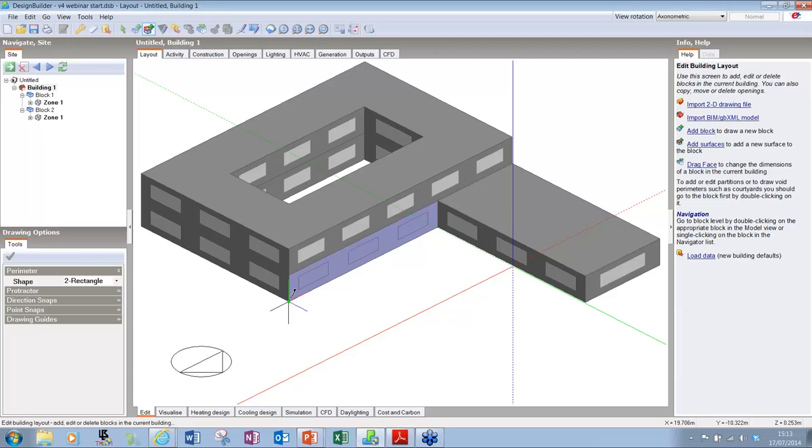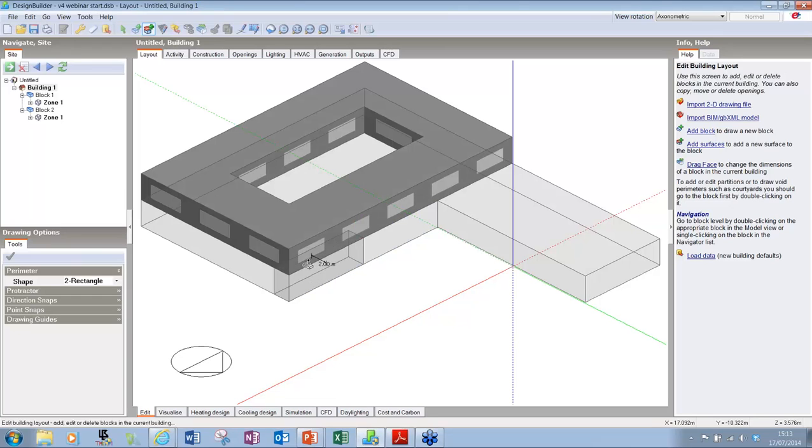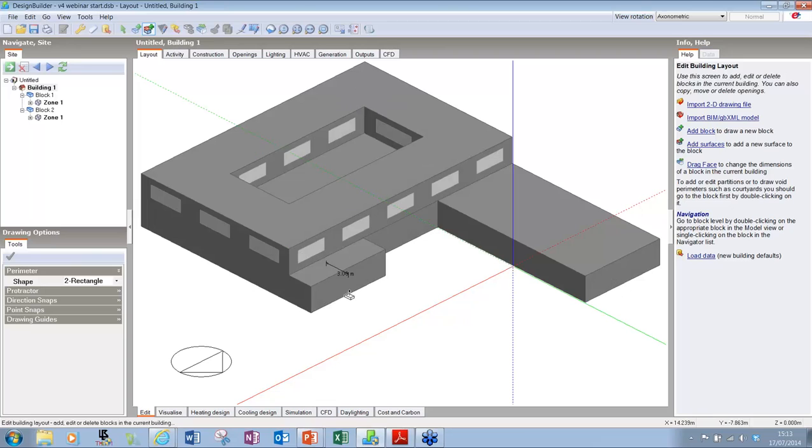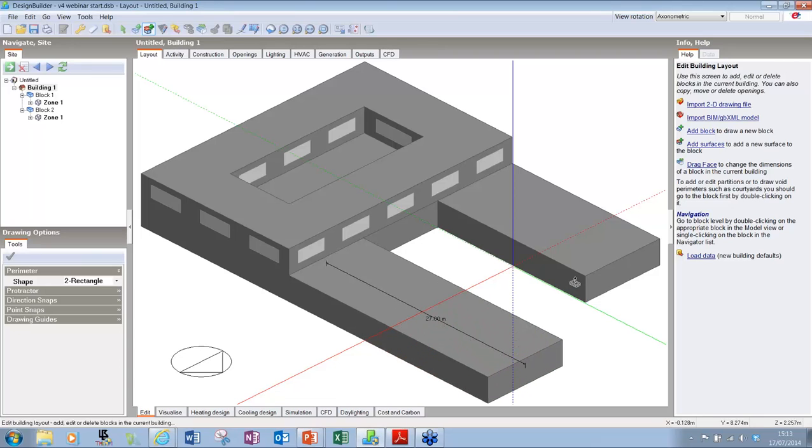Note how easy it is to select that part of the facade and define the perimeter using the centre and end snap points. And I'll now drag that part in either a positive or negative direction. Here I'll extend it so this part of the facade mirrors the leg opposite to it.